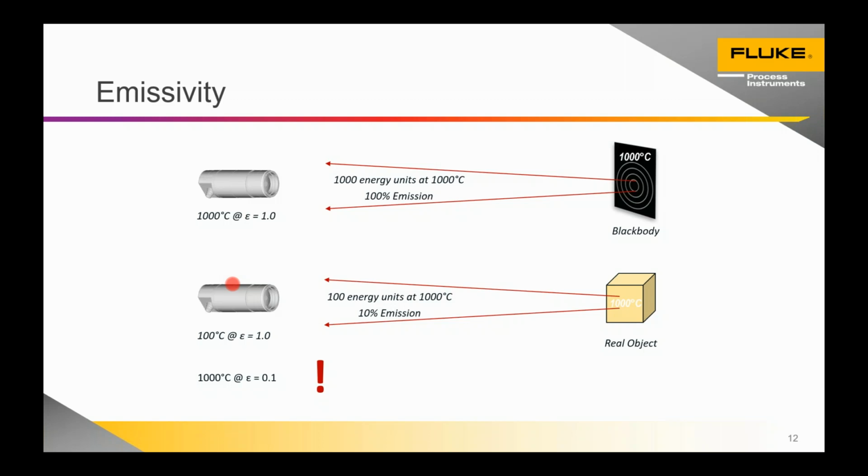So you don't get any improvement by being close up. Where you can improve repeatability is using the unit at its focus point. You can use it out of focus. It doesn't mean the reading will drop off. It just means that's essentially where your spot size is sharpest.